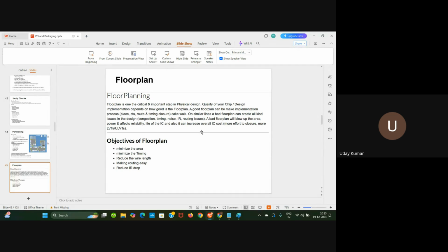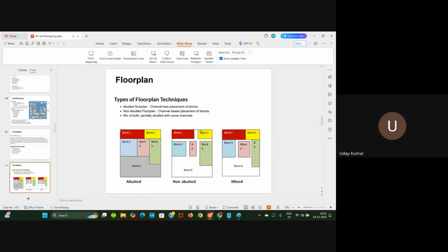So the floor planning. Floor plan is nothing but we need to allocate some area for the chip, and it's obviously either a rectangle or a polygon. That's for sure. And then we'll have macros, hardened macros. I have told you about hard IPs, which are already hardened, and we'll buy from them. Similarly, we'll have hard IP, hard macros for the memories and all, and we'll be placing them previously.